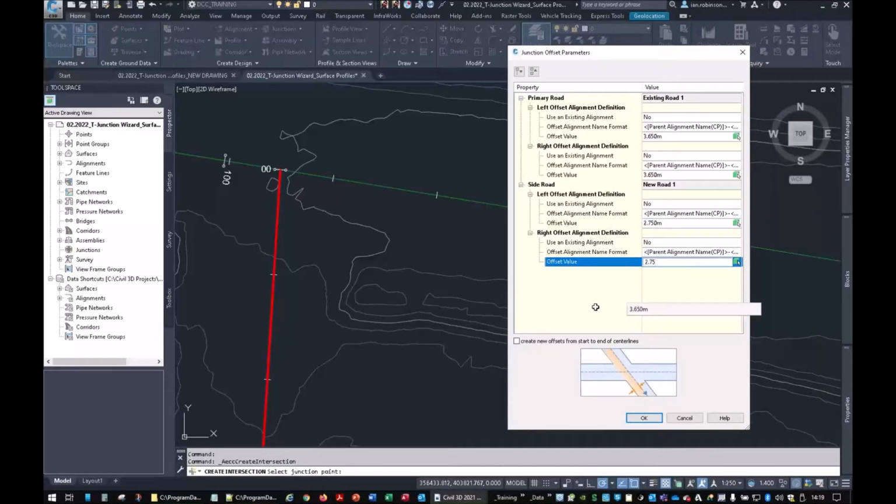That's it. If you are putting narrower roads on, like 275 for this road here, if you don't tick this box here, it will only put the offset to about here, about 10 meters beyond the junction, somewhere around there. And of course, because I'm using a narrower road, it's going to target them. And when it goes beyond the offsets, it will widen it back to whatever the assembly that we're going to use is, and you'll see that in a minute. It'll widen it to whatever that is. So I suggest you always tick that box. That would be my advice. There are reasons not to, but most of the time it makes sense to have that ticked. So we'll hit OK. I'm happy with that.